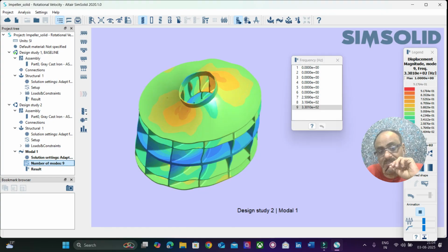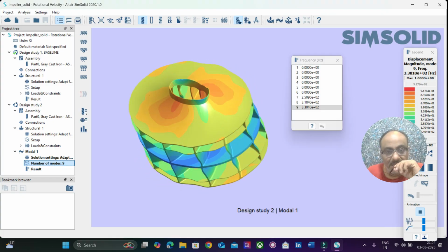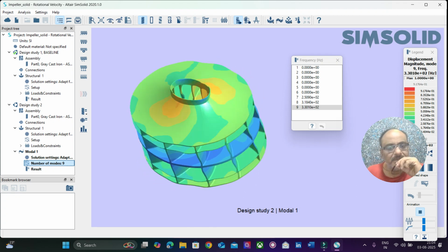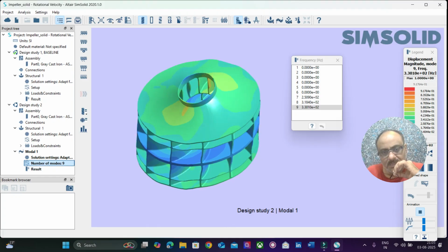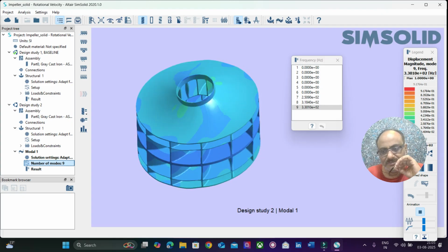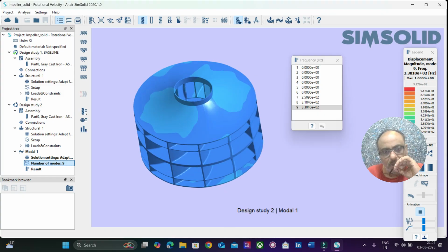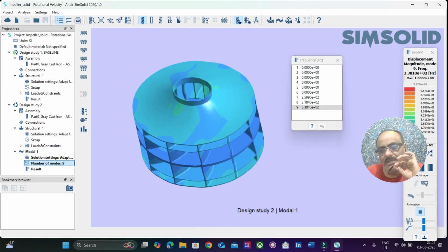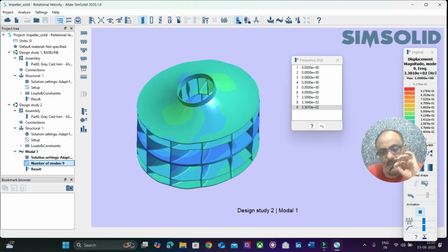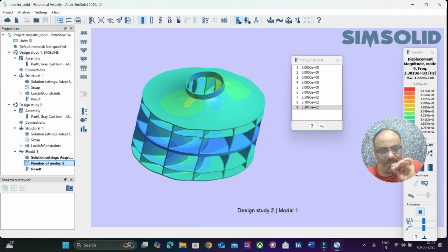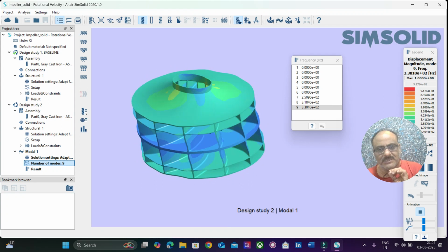But what we did in the previous optimization, the previous simulation, is introduce a crown on both the top and the bottom. The reason for introducing the crown on both is to avoid this particular tear, so that it's a kind of tension reinforcement. We are providing a crown on the top so that the tearing stresses are distributed across the crown. So the probability of failure is very low when there is a crown attached to the shroud. This is the way the predictions, or the inferences, are done.